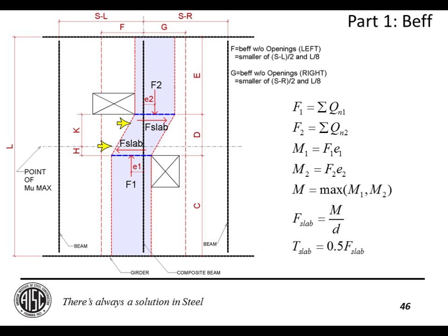Right? So you get a little bit of extra effective width at the penalty of having to put some reinforcing in your slab. If you're going to do this method, I recommend you read his paper because there are a couple additional caveats and some design examples that will help you make your way through that solution.